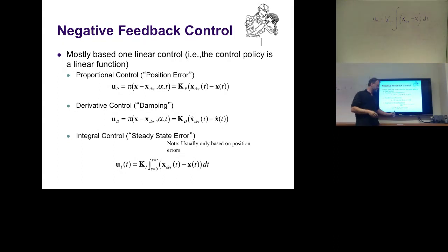So what is this useful for? Here is essentially the problem of P, proportional, and D control. Let's assume you're a system who wants to push against gravity. I want my arm to be up here. But how am I going to do this? I only have a P and a D term, so only proportional derivative control. My desired velocity is 0 up here at a particular position. We'll calculate this in a second.